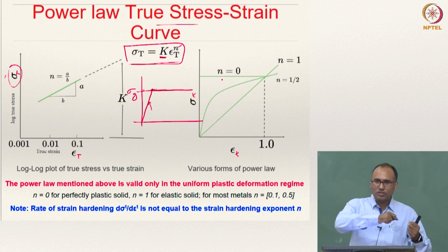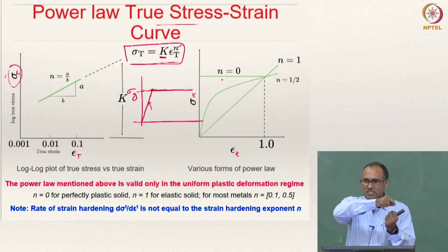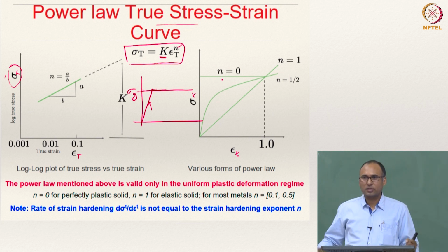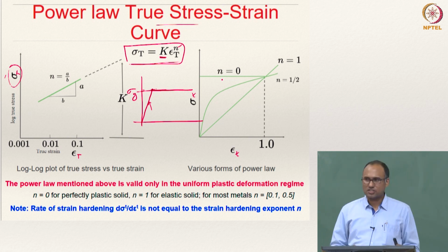So, and hence, at constant stress, you are able to have deformation. That means you are able to impart strain to the material, right. This is an idealization. Typically, there are no materials which can actually show such a behavior, but it is an idealization. This is what is called elastic perfectly plastic material.